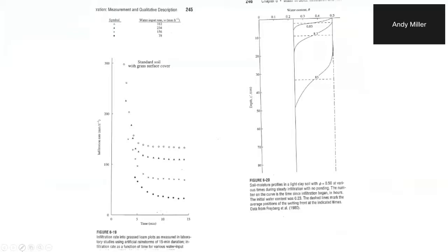You might remember the experimental images I showed you last time that showed there's all kinds of other stuff going on. There could be macropores, you get water that bypasses a zone, and then water gets hung up at different places. So the real soil is always more complex than anything we simulate. We just don't have the ability to capture all that information. We can't even get the data. So the question is, can we do approximate methods that capture important enough aspects to be reasonably useful for prediction purposes? So what they're showing you here is that's after 0.83 hour. This is after 8.3 hours.